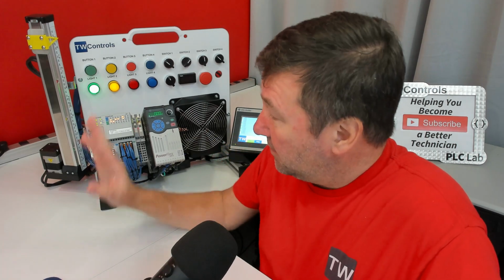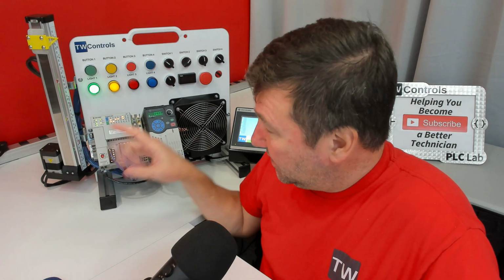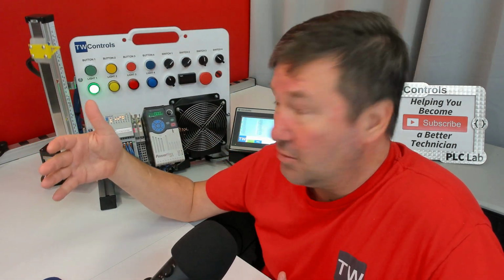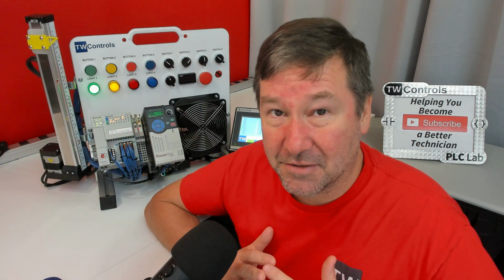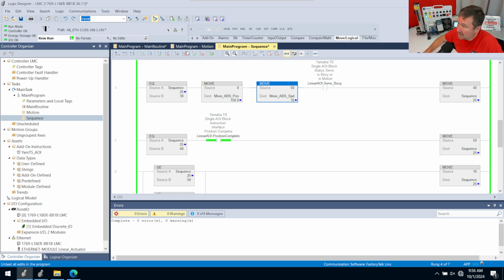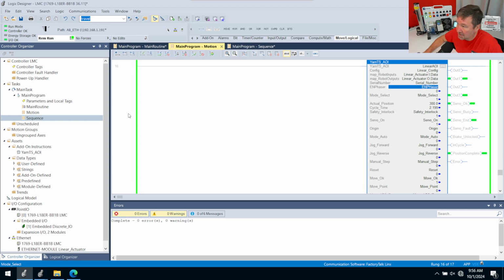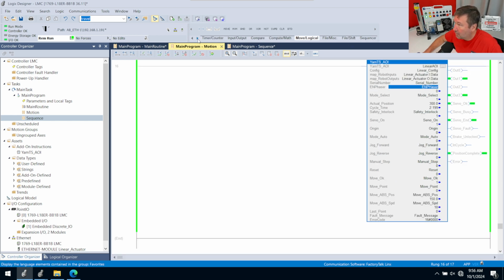In our previous videos, we have configured our linear actuator to integrate with our CompactLogix PLC. And then in the last one, we went through the basic sequencing to do the bulk of your pick and place applications. Now, we've done all this without needing any of the motion instructions in Studio 5000. And that's what I love about using this YRG actuator: you have a single instruction that pretty much does everything. We also do have a whole motion set of instructions up here.